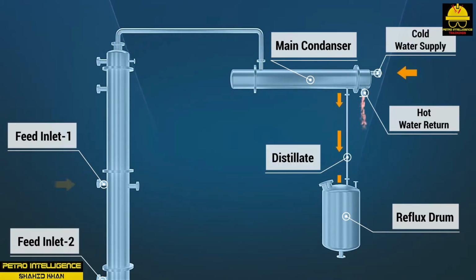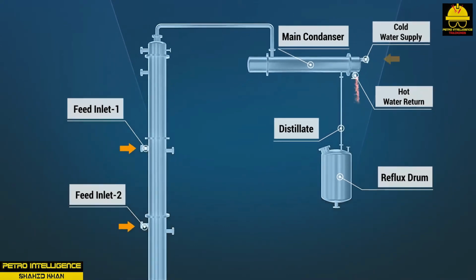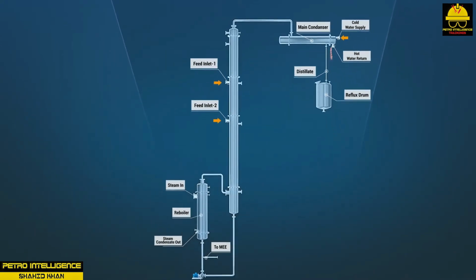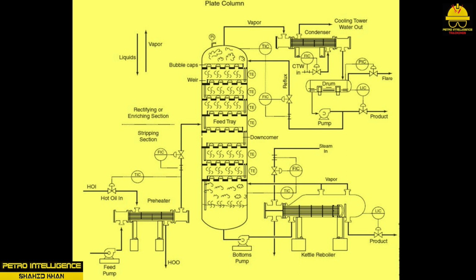During the distillation process, a mixture is heated until it vaporizes, then is recondensed on the trays or at various stages of the column, where it is drawn off and collected in a variety of overhead, side stream, and bottom receivers. The condensate is referred to as the distillate. The liquid that does not vaporize in a column is called the residue. During tower operation, raw materials are pumped to a feed tank and mixed thoroughly. Mixing usually is accomplished with a pump-around loop or a mixer.